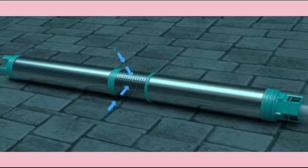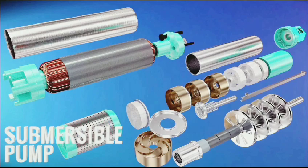Cavitation does not occur in the submersible pump because in this system water is pushed rather than pulled, and this reduces the chance of negative pressure head in the system. The high pressure head, flow rate characteristics and the ability to be immersed completely in water make the submersible pump an ideal choice for borewell lifting, firefighting, oil well lifting and many other great applications.